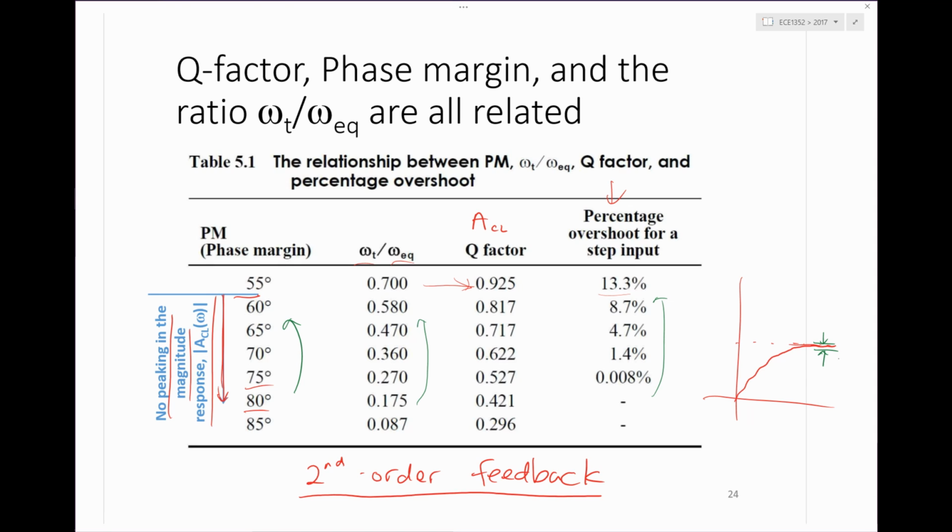The phase margin you want then depends on X, okay? If X is really loose, then maybe I want one that rings a bit, right? As long as it stays within X, it'll get there faster. But once we start making X really, really tight, that pushes us to higher phase margins, because then we need smoother settling. We actually get within that boundary sooner by not having any ringing if X is really tight. So it depends on what you mean by fast, like how accurate you need it to settle. Yeah, so you're right, and that's not captured here.